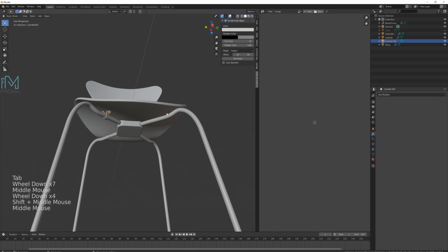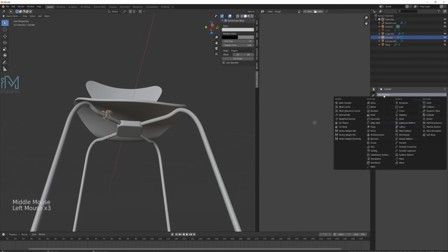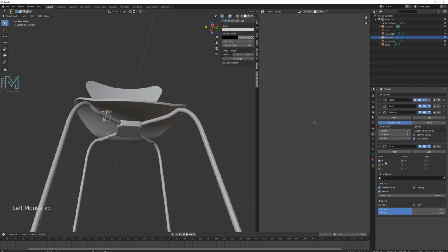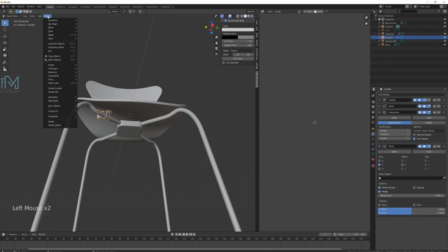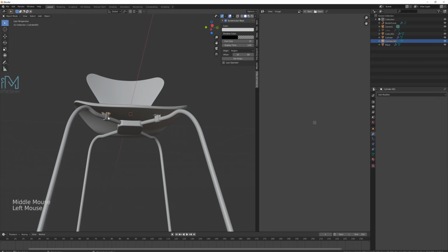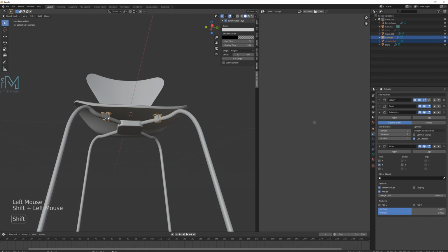Okay. And these are no longer mirroring. I think it must have removed that modifier, unless I did something that I missed. Oh no! Shift S cursor to selected and select the object and click object and set origin to 3D cursor. Okay, and click the bolt and then click this one, do Control L and copy the modifiers. But I'm guessing the origin.